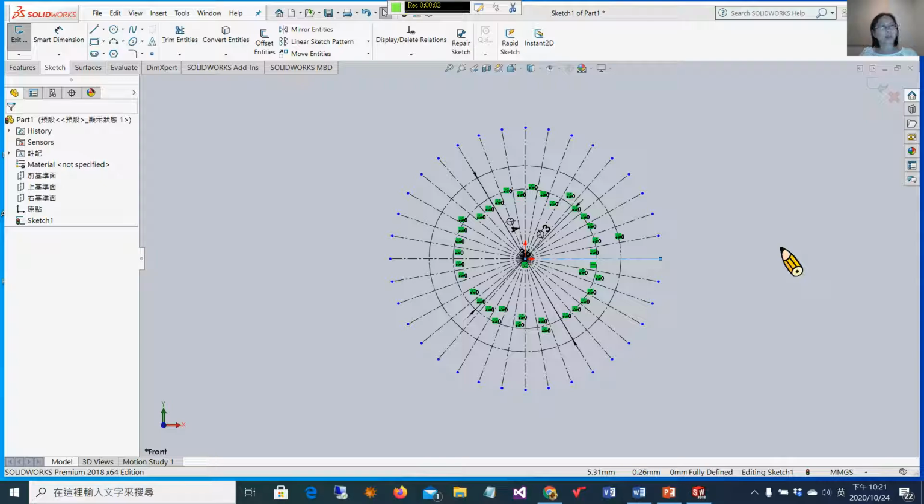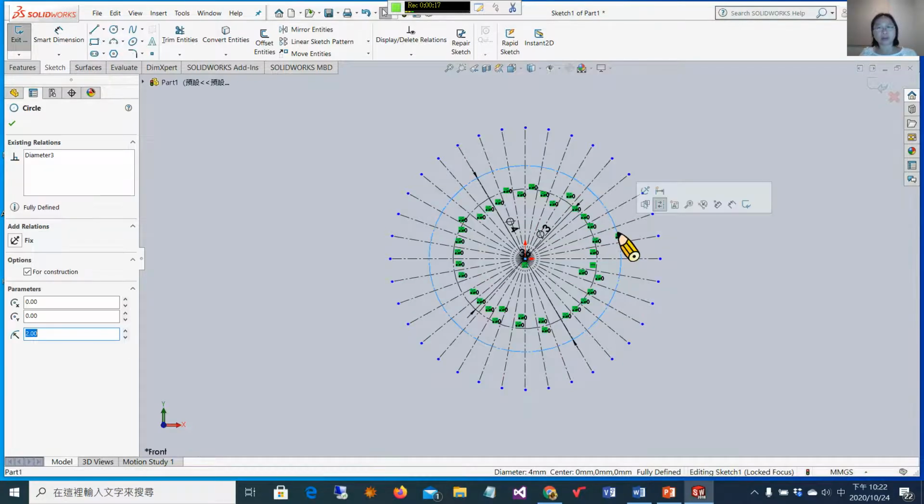We need to get the roller center positions for each roller position. Plot a line segment on each ray line outward from the prime circle. Its length is the same as the follower displacement.